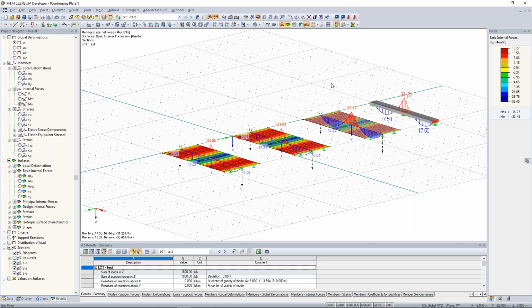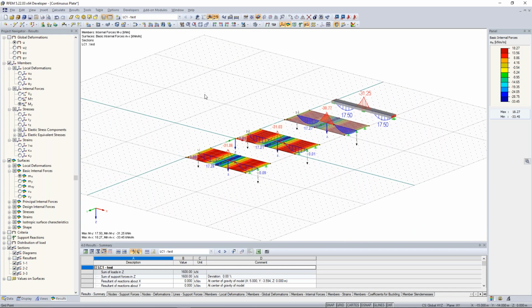Maybe I can answer the next question. Are we conservative by considering a bigger or smaller FE mesh? It's up to you. How big is your model? It depends on several things. First of all, when you have a really big model, it's up to you how you want to choose the FE mesh sizes, because the smaller the FE meshes are, the longer your calculation needs. But the more exact results you get. Sorry, I had to look up this word.